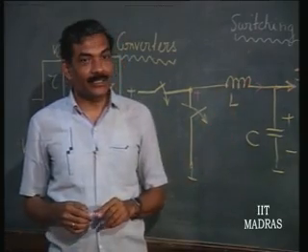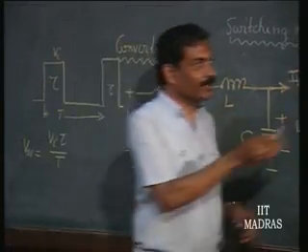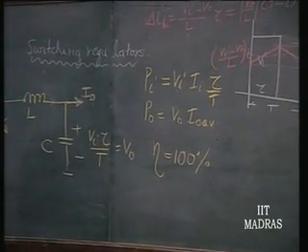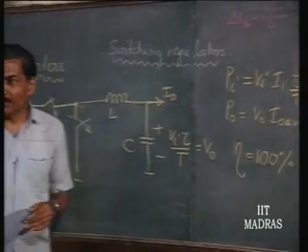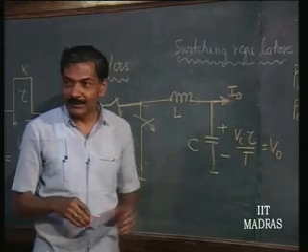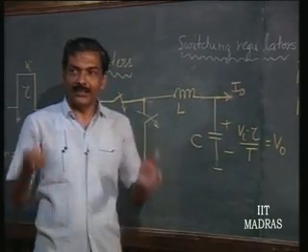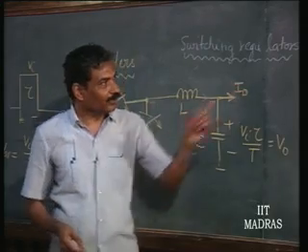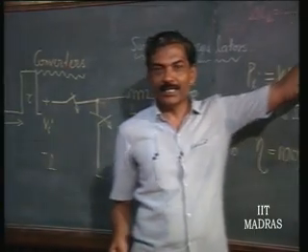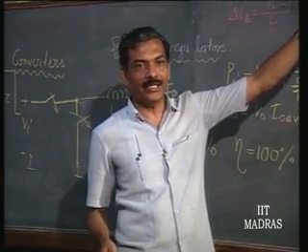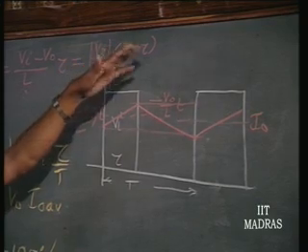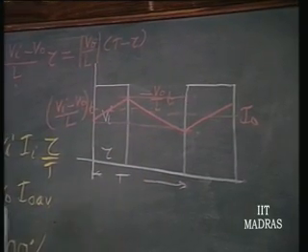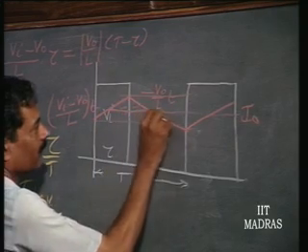How do you find out the voltage across the capacitor? You know the current waveform, triangular. So, what is the waveform of voltage across the capacitor? What is the value of voltage? How do you find out? Integral I dt, you know the current. What is integral I dt pictorially? No, no. What is the operation integral I dt? Area under the curve.